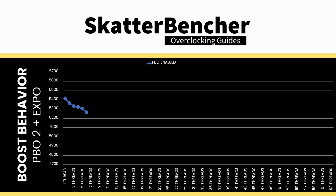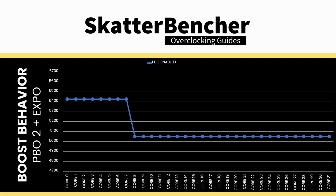the boost frequency at one active thread is about 5416 MHz, and the average boost frequency gradually trails off to 5099 MHz when all cores are active. In light single-threaded workloads, all cores in CCD0 can boost to 5424 MHz, and all the cores in CCD1, 2, and 3 boost to 5050 MHz.